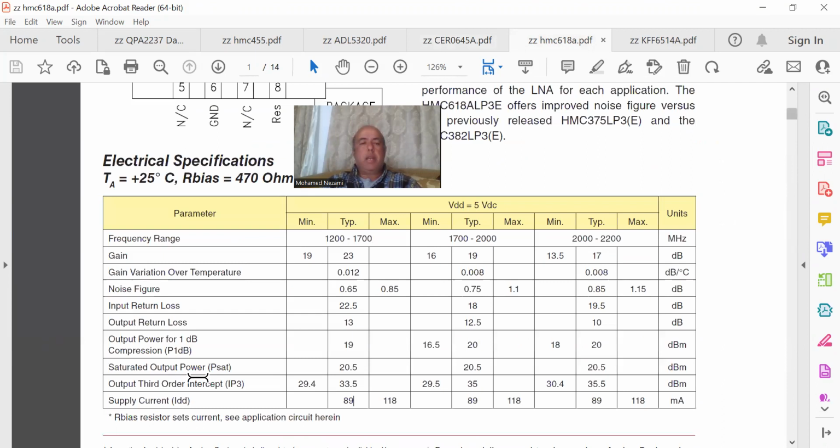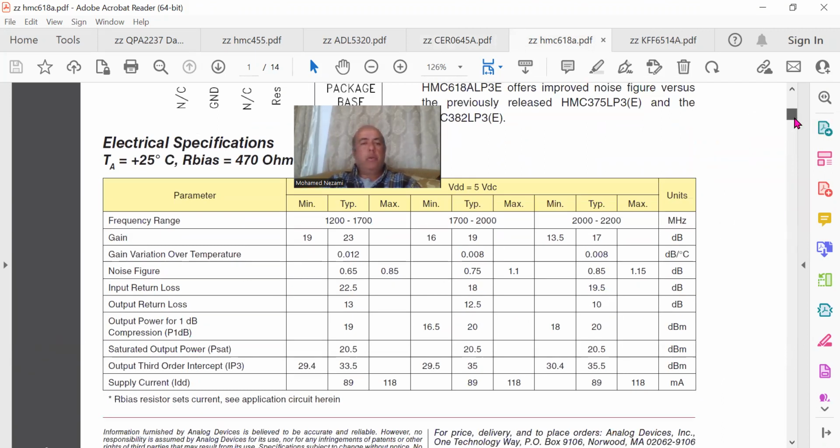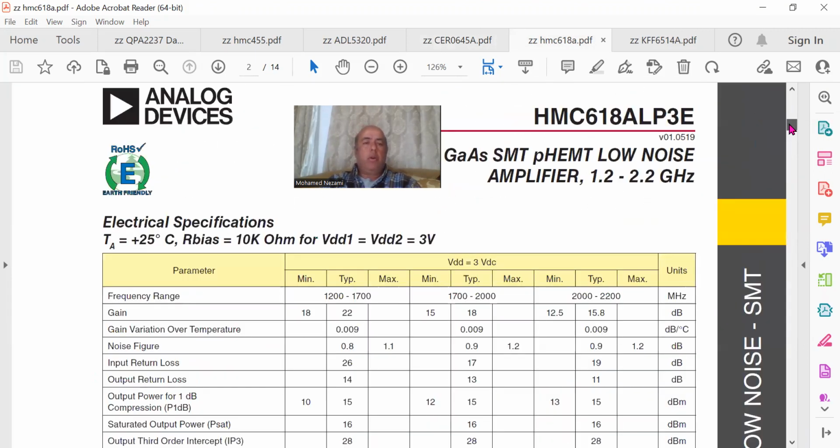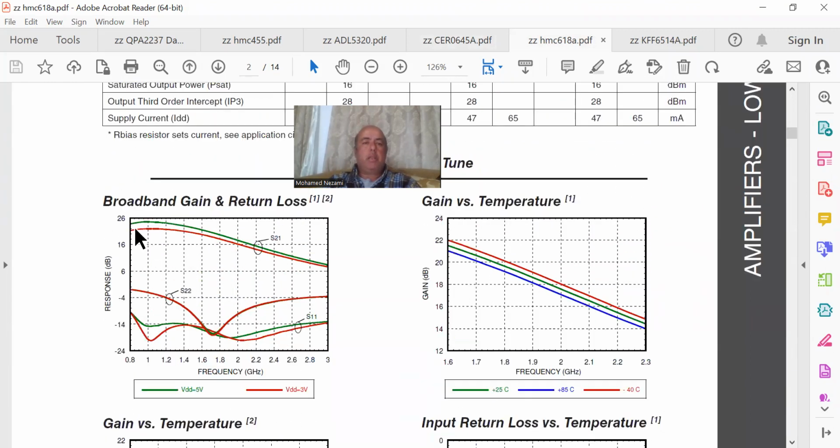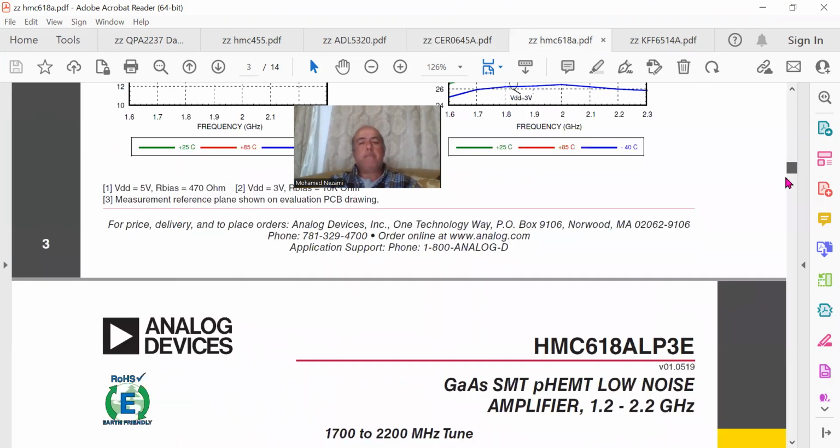So this is the data that I captured in the model, for the linearity. They give you all of these so that when you generate the frequency dependent model, you use these graphs. What I do is I digitize them, store them in an Excel sheet, and load them into the simulator.